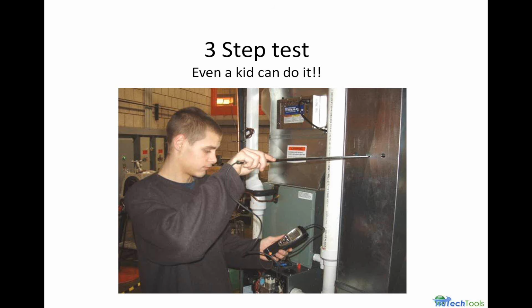Those holes, the outer 2 holes, should actually be drilled at about 1 inch off the surface of the wall, then a center hole to get an accurate reading. This is an older picture before I really knew what I was doing with airflow, and since then, we move in about 1 inch off the ductwork typically and measure from the side, the narrow side of the duct, because the probe's about 36 inches long. So you only have to make 3 holes in the duct then typically. Unless you're doing like a 12 or 14-inch wide drop, then you might have to drill a 4th one in there. Typically, we'll use a plastic plug to plug those holes when we're done.